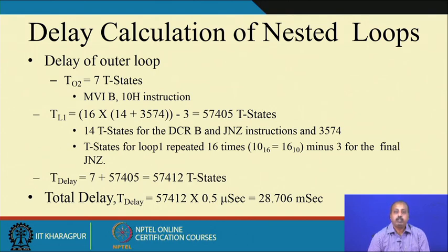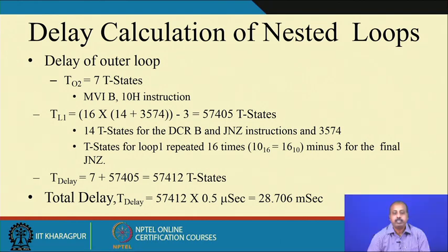So, this is the beauty of assembly language programming. If you do the same thing with a high level language program, we are not sure how much time these high level instructions will take, because that depends on the way the compiler translates the program into machine code. But if you are writing the program in assembly language, then the programmer will know the exact instructions put into the program, and accordingly can calculate the delay, the time needed for a program. So, assembly language programs are very important when you are looking for very precise timing information.